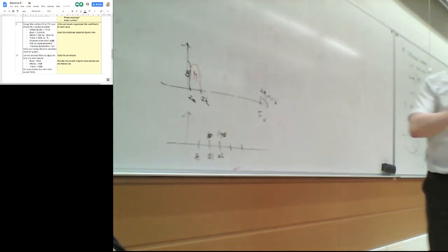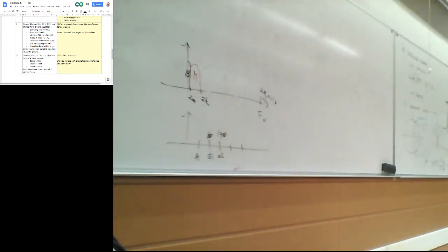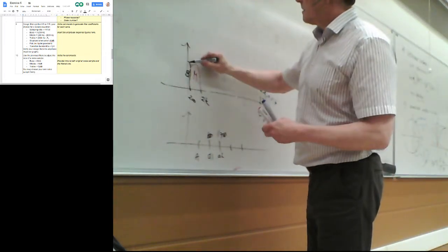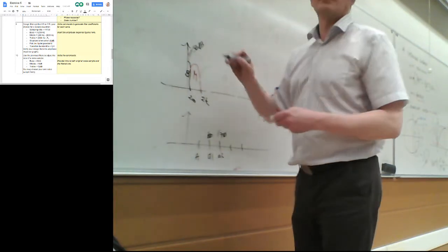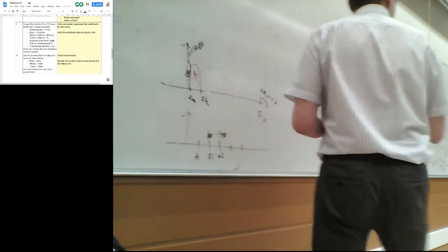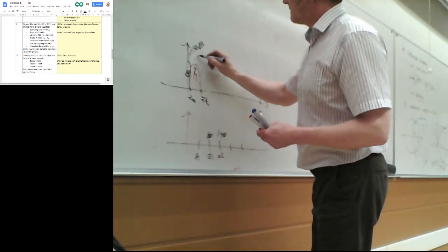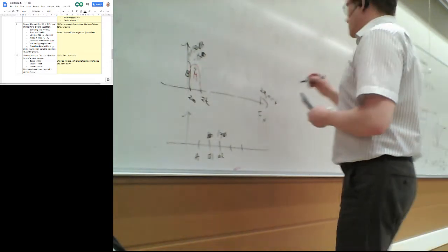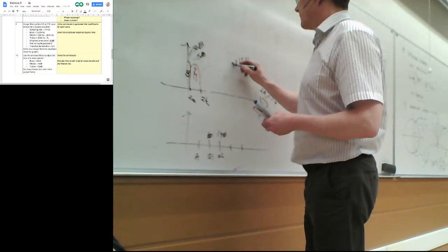Filter bank, 3 filters. And then you would have adjustment of each of those bands so that you have bass plus 30 dB. Decibels again. Middle band minus 15 dB. And then the high band plus 12 dB. Okay.